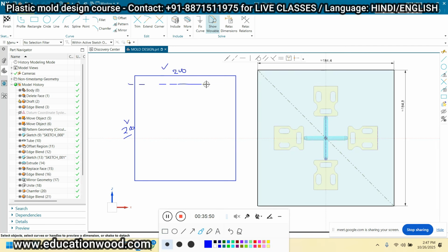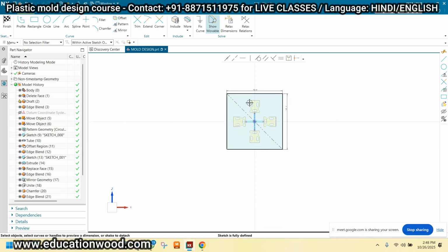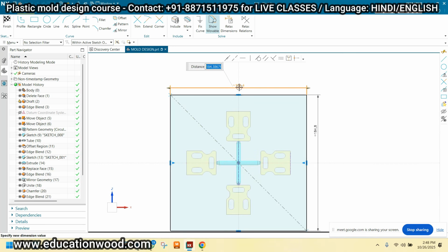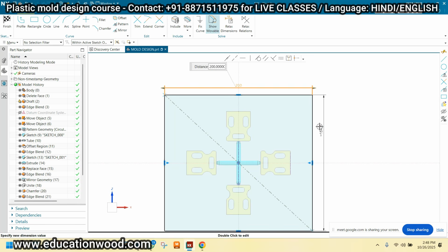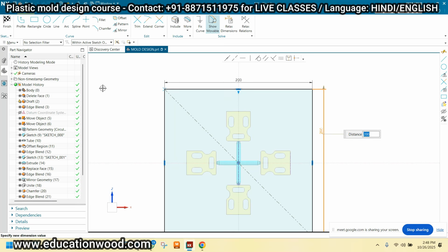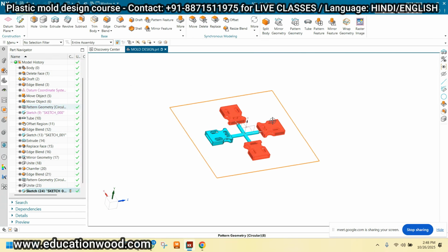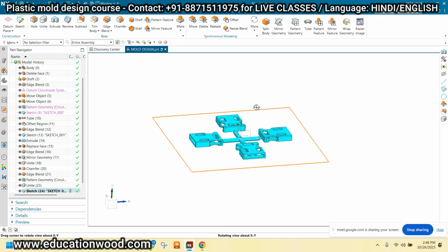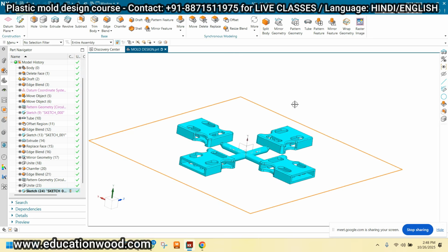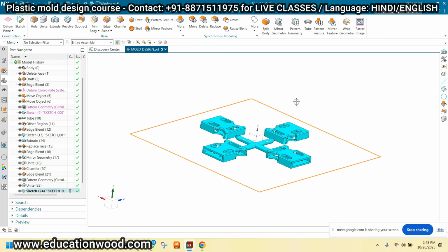Then you have to cut from here, cut from here, and then make the size, right? So this will produce more complexity, more cost. So it will increase the cost. So just take the standard dimension: take 200 mm and 200 mm. Understood? This is very important. It is a very basic thing, but very important, right? If you are making the mold, our concern is we don't want to increase the mold cost. We want to reduce the mold manufacturing cost. Okay.